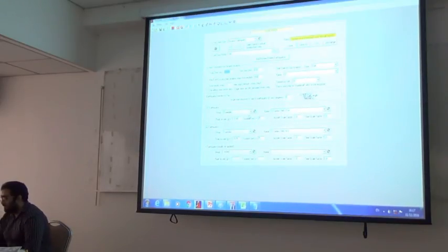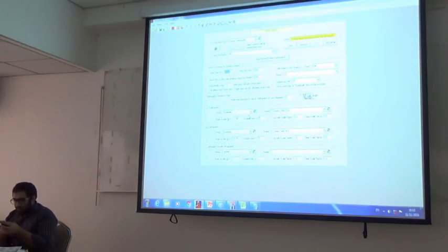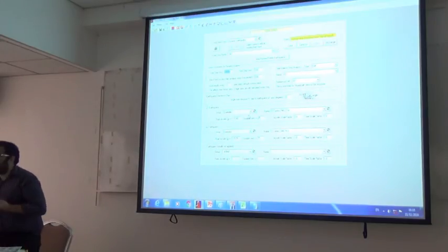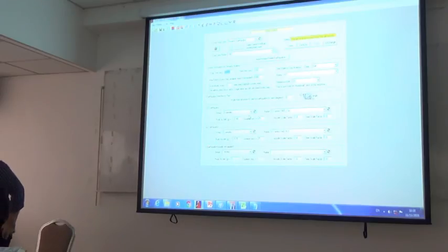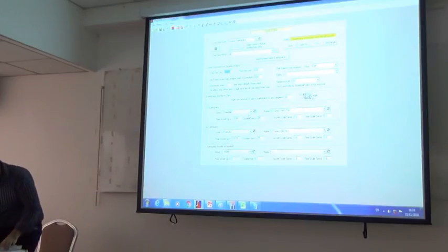What's the reaction? Story shear? Yes, story shear. Just plot the story shear of the dead load plus 25% live load combination along the height from ETABS and along the height from Perform 3D. If the two curves are not matching at some level, where it suddenly increases, then we have to check that level's loading application.